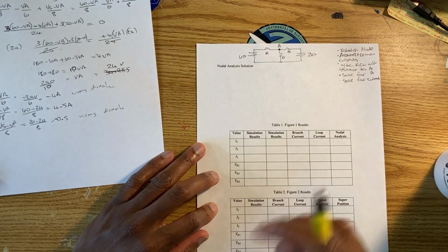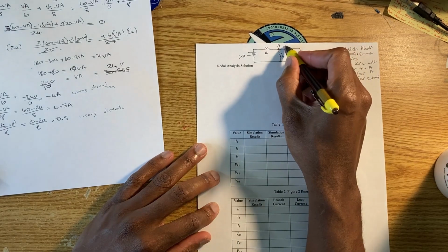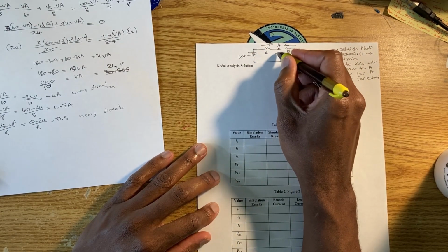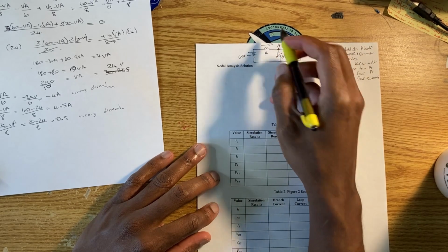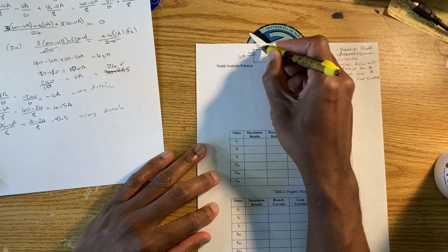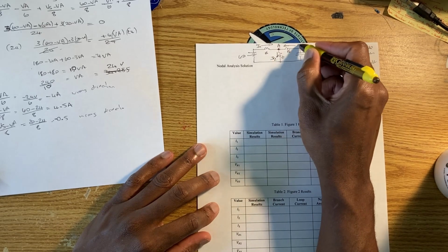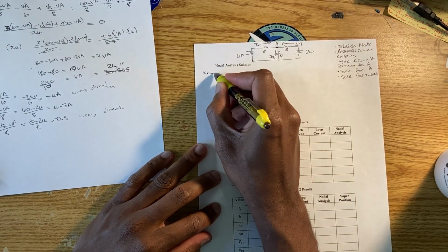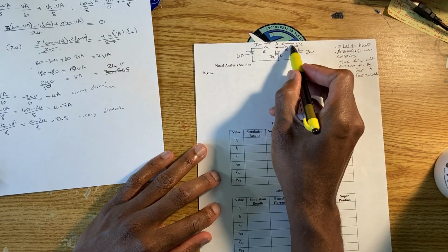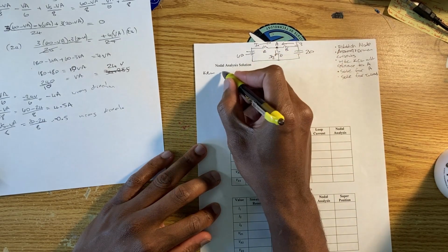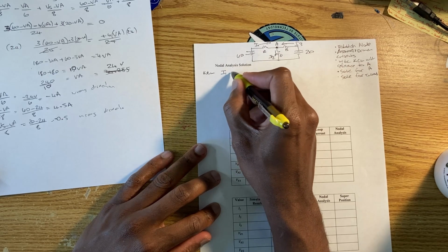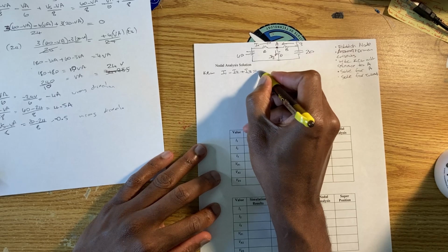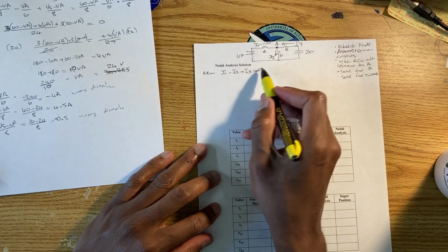All right, so let's try to do this. So again, here, let's just assume that the current is coming from here, and then the current is going down here. So these two currents are adding up together. Of course, we'll call this one I1. This one is going to be I2. This one's going to be I3. So if you write the KCL, for this equation, I2 plus I3 is going to be equal to I1, or we can say that I1 minus I2 minus I3 is equal to 0. Now we're going to rewrite that with reference to A.